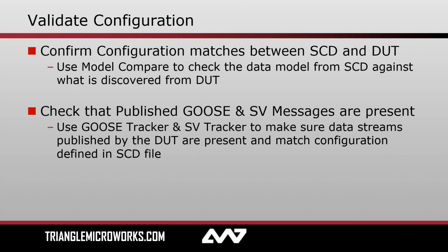So when we have a configuration, this might be in the form of an SCD file, which describes the capabilities of all of our devices, or it might be a CID file, almost like an extraction from that SCD in some ways, that contains all the configuration information for a single device. In either case, that is ultimately pushed down onto an IED, along with maybe some other settings that are vendor specific. And then that is what configures that particular IED.